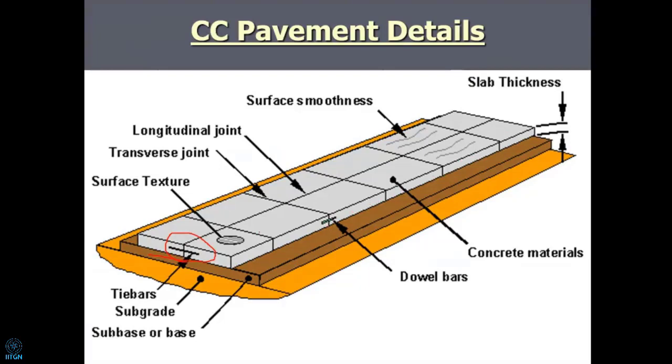Okay, so below this slab and above the subgrade, there is also what we call a base or subbase. Always this is a base or subbase. I will talk more about that later if time permits. Otherwise, in the original way of designing pavements, they were only considering the presence of the subgrade, that means they were considering the modulus of that only, and then design was done.